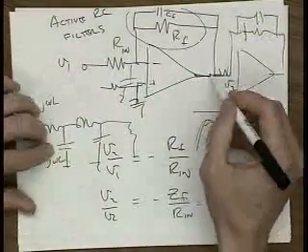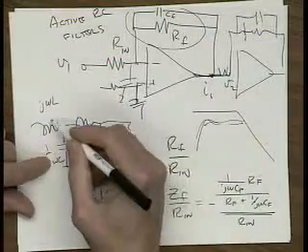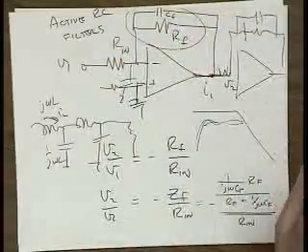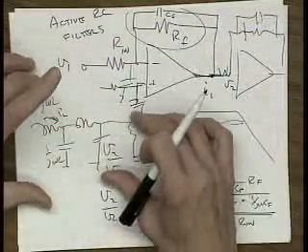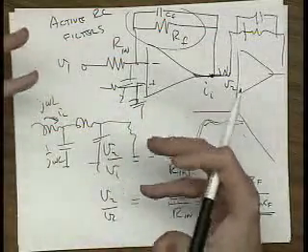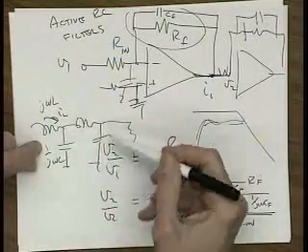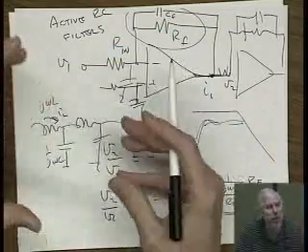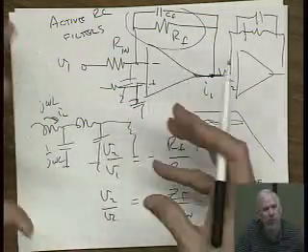So what you do is this node here, instead of representing a voltage, would actually represent a current, maybe the inductor current. And there's a much more complicated structure that you put these things together. When you do that, you can model these LC networks and actually have very good characteristics. And so that's often done. In fact, digital filters, even yet, are based to a large extent on the analog LC-like networks quite often, because they have better characteristics. So this is all to do with filter design.